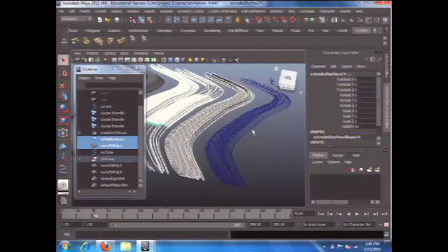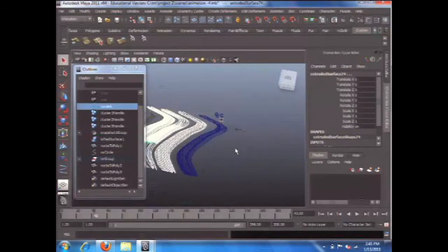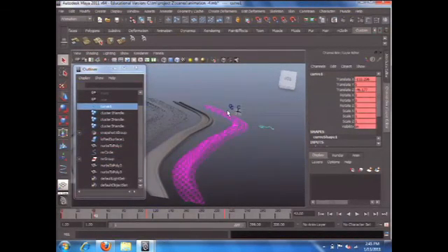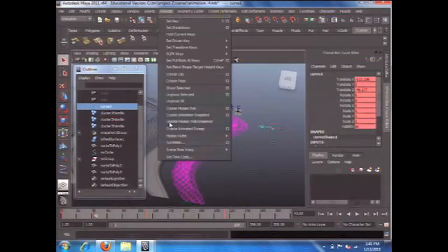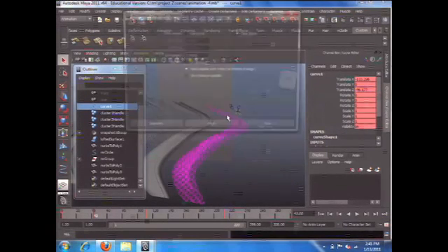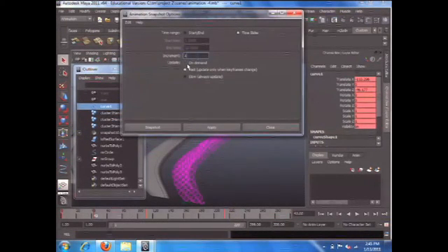So I would rather do this from beginning. You already have this animation, right? You have the animation cluster. The only thing you need to do is just select this guy one more time and go here. Go back to animation snapshot, create a new one with increment as 1. So this is the easiest way to do. Just redo it. Should be good.